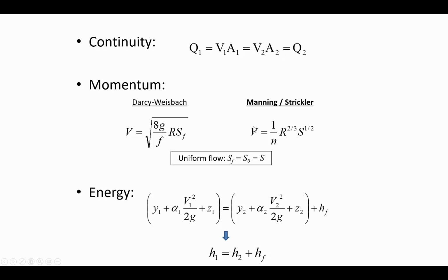All right. So I told you that we don't usually have f values for open channel flow. I mean, there technically is a Darcy-Weisbach equation that relates flow velocity and f values in open channel flow, but the Manning equation is far more convenient and gives us a good enough answer so that we can use constant n values rather than variable f values in our calculations for velocity.